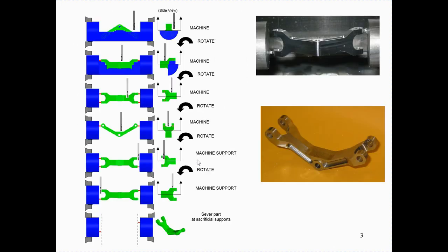CNC-RP takes an approach of machining parts about a rotary axis. We make parts from round bar, and we do removal operations about a series of orientations as opposed to a 3D printer that attempts to add metal in one direction. CNC-RP automatically chooses these orientations using a series of algorithms, chooses tooling, designs a set of support structures that keep the part attached to the stock throughout, even tells the user what diameter and length of stock to use